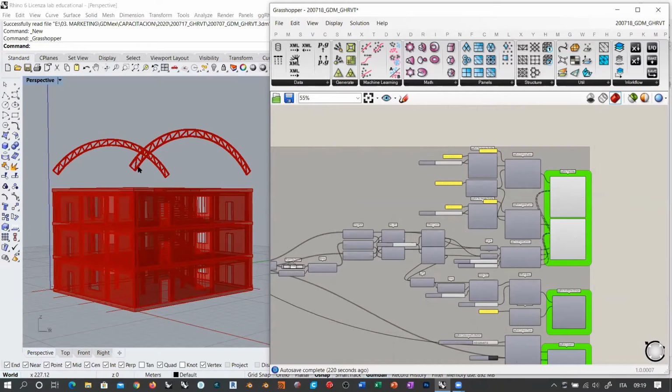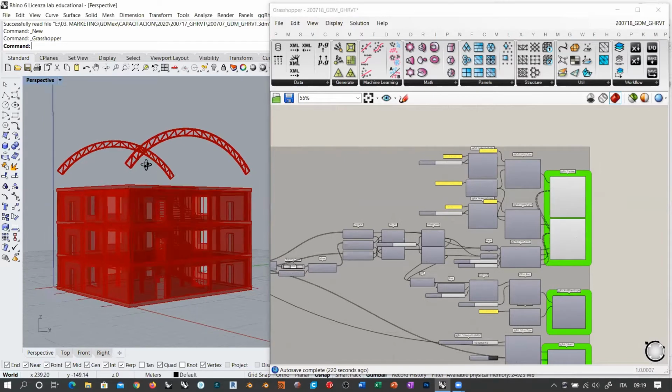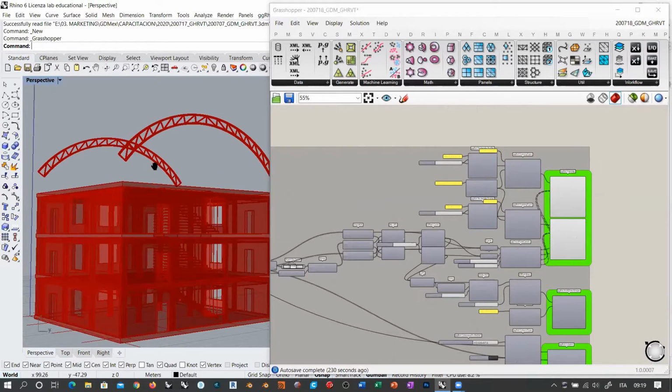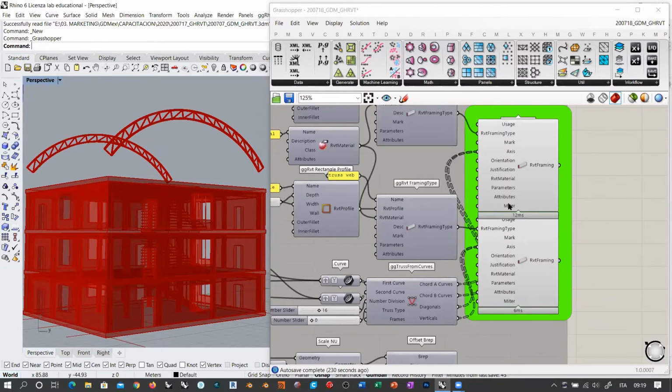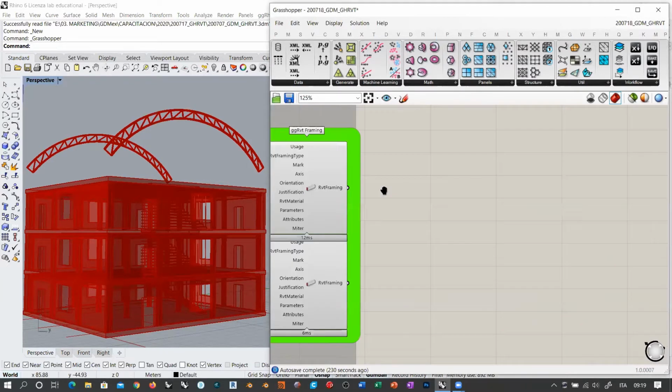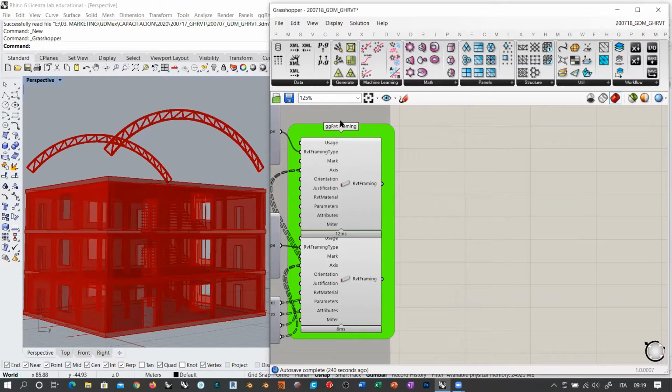Tweaking this kind of thing here can be time consuming, and also there are some processes that you can put in place here in Grasshopper and with Revit tools, because you see that there is metering. We were already anticipating something about metering. It is basically when you have an element like this. Let's say we are looking at a beam from the top view, and it ends in this point, right? And then you will have another beam, for example, connected here that ends in the same point, but they don't relate to each other, okay? They just end in this point.